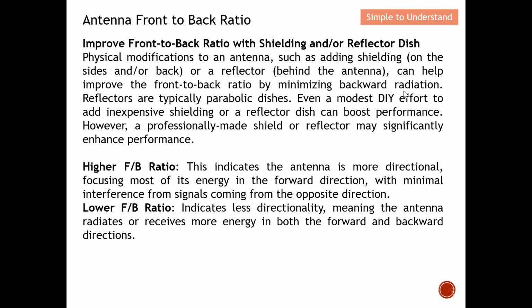So basically from here you can see that if we put some form of shielding or some form of reflector, the front to back ratio will be higher, because we minimize the back signal as much as possible. Even a very simple DIY effort to add a specific shielding or a reflector dish can boost performance. However, if we do it professionally, with proper shield and reflector, this will definitely enhance the performance.